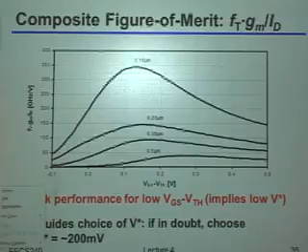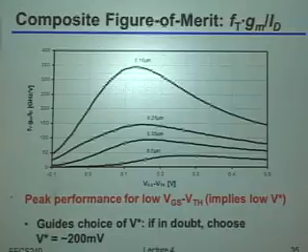So let me ask a couple of related questions. Let's say that for whatever reason, you're dealing with some standard that says, okay, I always have a certain bandwidth that I have to be dealing with. This could be like a radio baseband or some chip-to-chip communication or something like this. So if I scale my technology, and I want to get the best possible power efficiency for that given standard with that given bandwidth, what do you think will tend to happen to the V star that you will choose? Yeah, you're going to tend to choose it lower. Why?